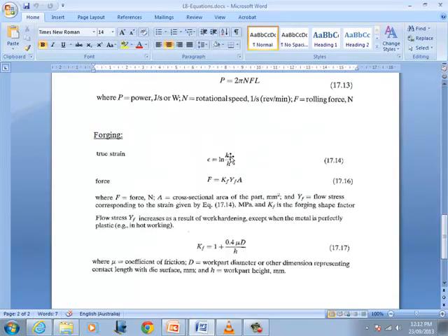We've got initial height, which is 75. We've got current height, which is 62 now. So strain at this height will be different through strain. So we've got to compute new strain by making use of this equation, and then substitute this value of epsilon into the YF equation in order to compute a new value for YF. When you've got a new YF, you can substitute it here.